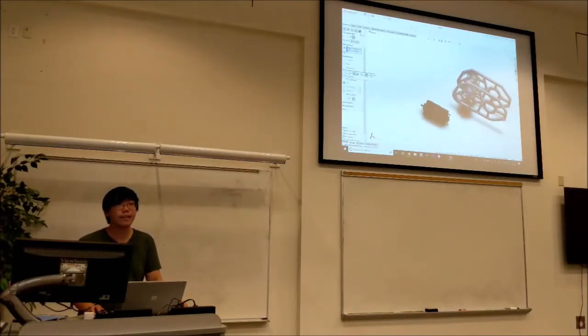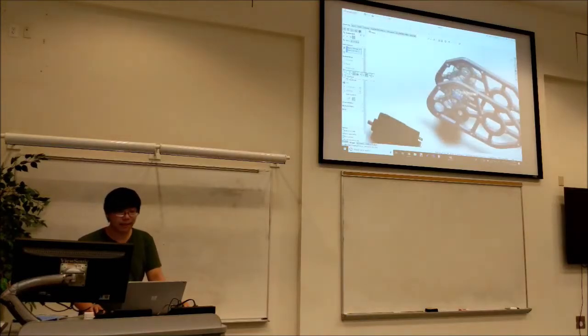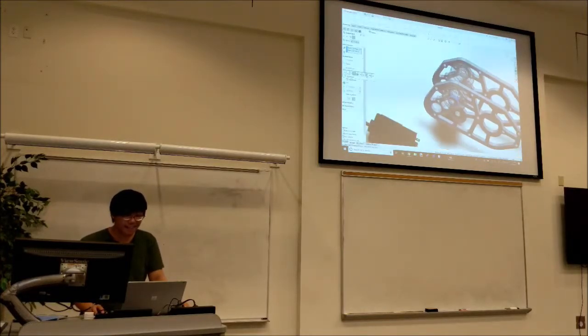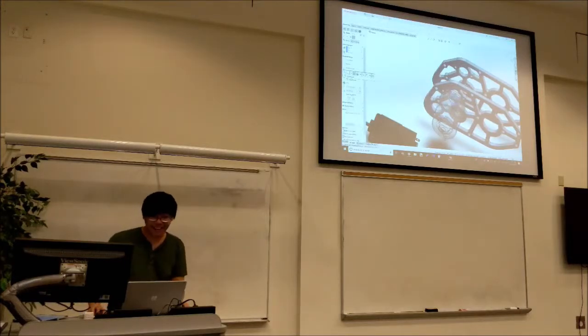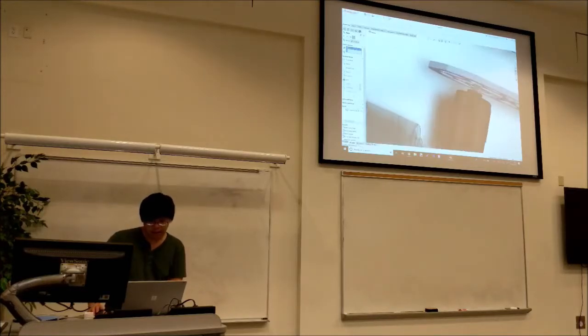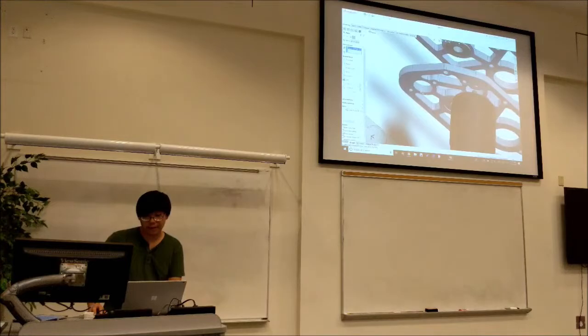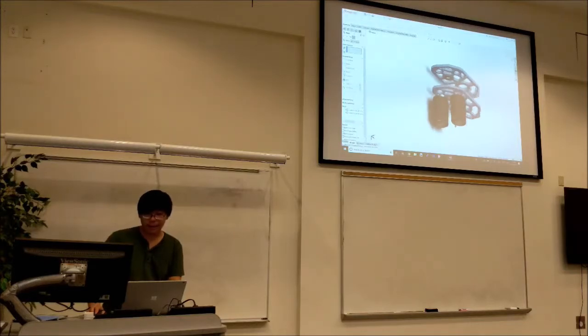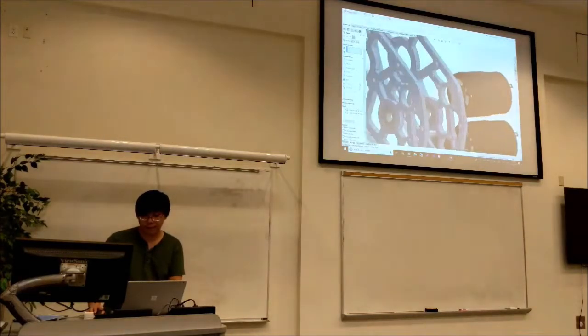For drivetrain, I would use CIM just to be on the safe side. I know a lot of people are pushing Mini CIM because of its efficiency, but in my opinion, I wouldn't do that at the moment. But yeah, so definitely for drivetrain, I want to run a gearbox like this, just because the 775 Pro can burn out easily if you're trying to play defense or something.